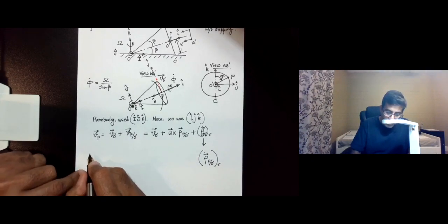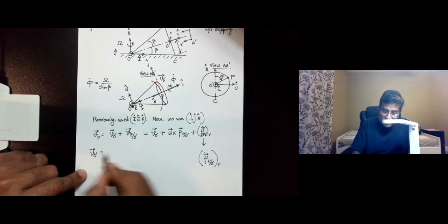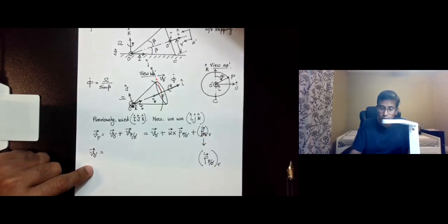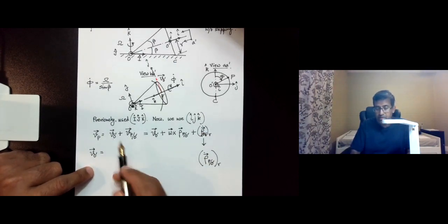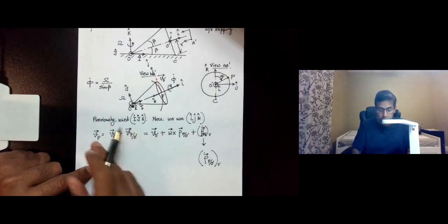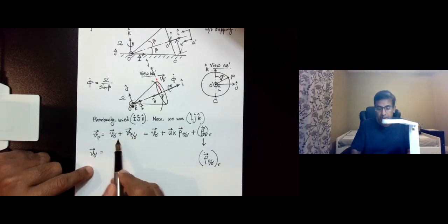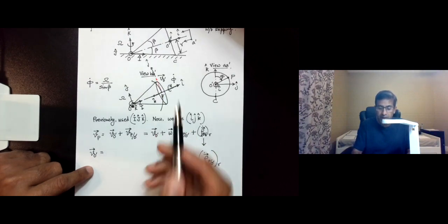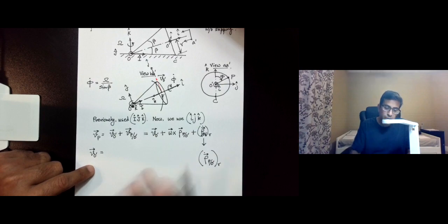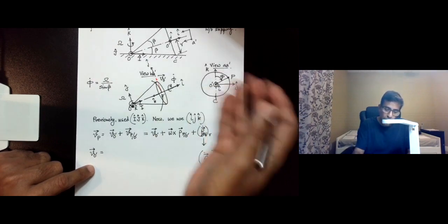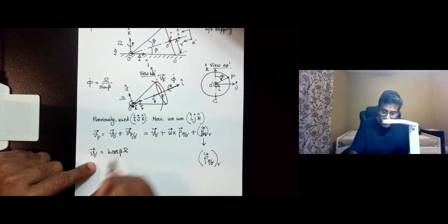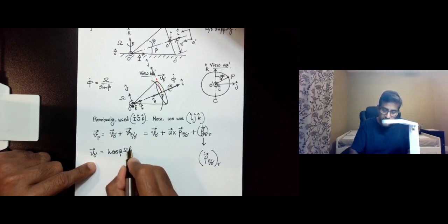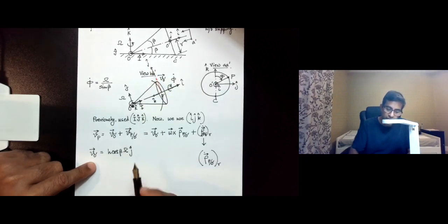Now V O prime, let's take these vectors one by one. V O prime is the velocity of O prime, and deliberately we chose the point O prime as our reference point with respect to which we are going to express the velocity of P. We deliberately chose O prime because the velocity of O prime is rather easy to express even in this small ijk coordinate frame, the coordinate frame that we are using now. And so that velocity is h cosine beta times omega, and it's in the direction j. So it's in the direction j, this red vector.